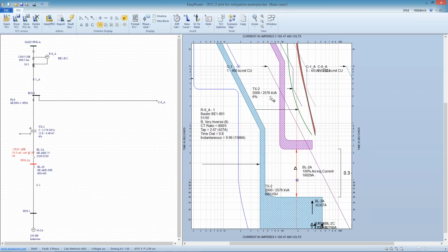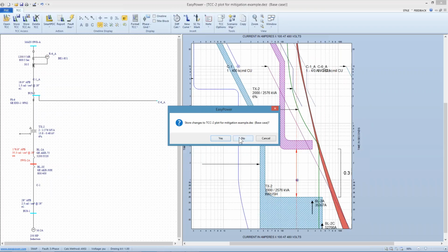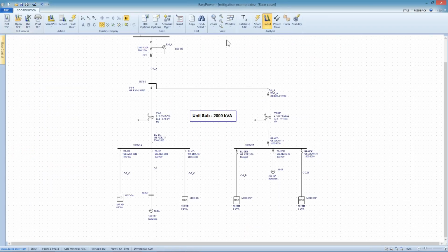All right, so the point I'm trying to make here is that we can be misled if we just look at one portion of the circuit or one report that's giving us incident energy calculations, and very frequently it's an iterative process where we look at the continuous arcing current path for any particular load, and as we go back to the OneLine diagram, that is something we can actually achieve if we're in a coordination focus and we look at a sequence of events report.